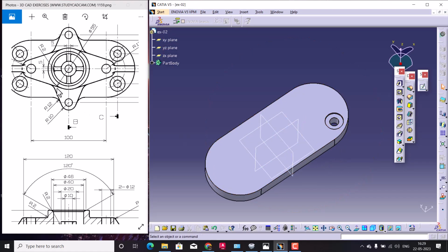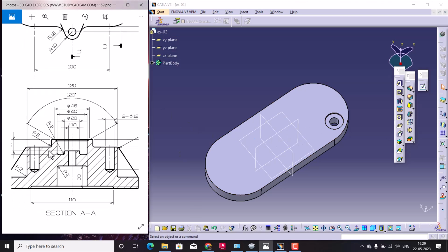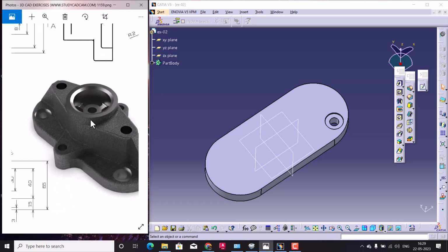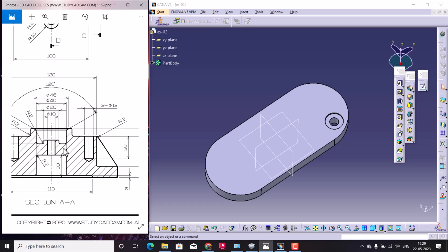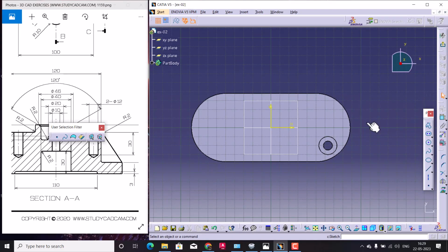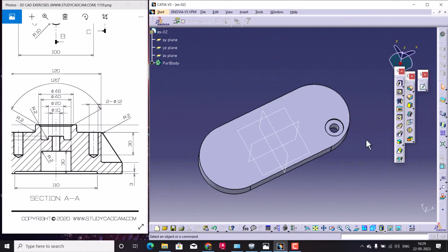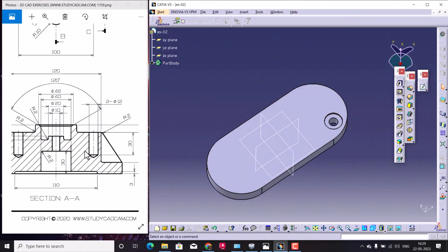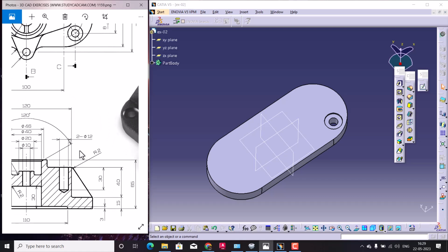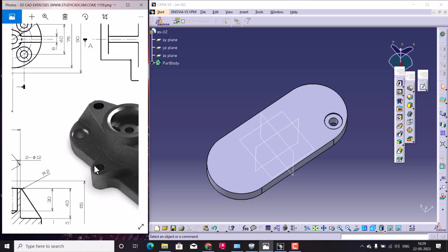So then maybe we will create this shape, or the center one, whatever it is lying, then side whatever it is there, we will make it up. So as you can notice, center portion is this one. It's like a cylindrical shape only. Just from here to the top it is going to come. Okay, so maybe when you are doing that, instead of creating in a pad from top view, we can do it as a revolve or shaft basically, so that the shape whatever we needed we will create at the beginning itself, instead of doing later.